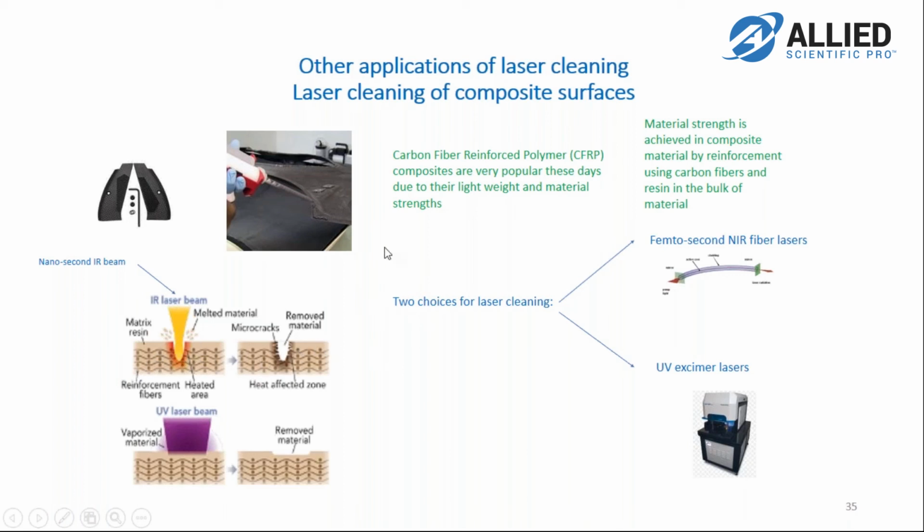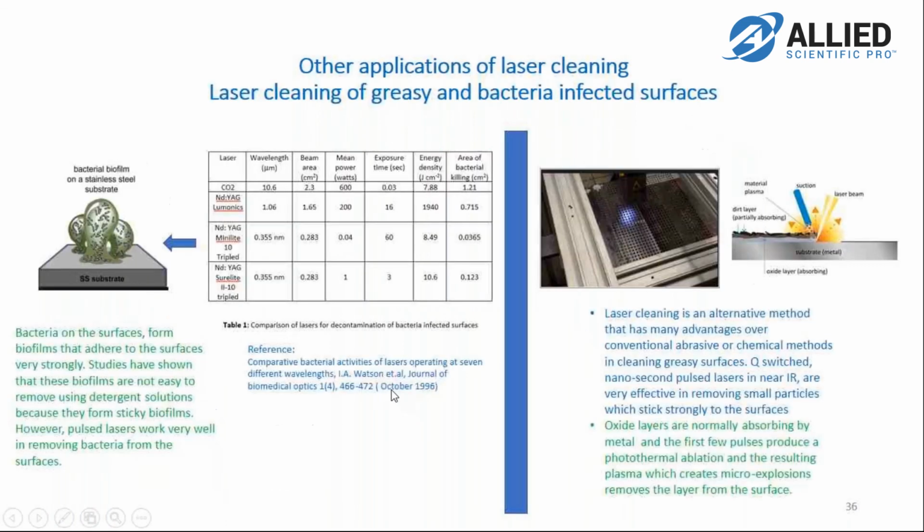So the way to clean the CFRP would be either to use a femtosecond near IR fiber laser, which has a very short pulse width, so thermal effects are less pronounced, or a UV excimer laser. So our laser would not work for this application.